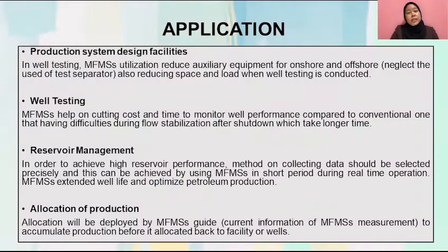Okay, we go to the application of multi-phase flow meter. The first one is production system design facilities. The use of MFM can reduce hardware needed on onshore, offshore topside and also offshore subsea applications. And the most important thing is the removal of the dedicated test separator for well testing application. Thus, use of MFM for the topside application can reduce load requirement and also reduce platform space.